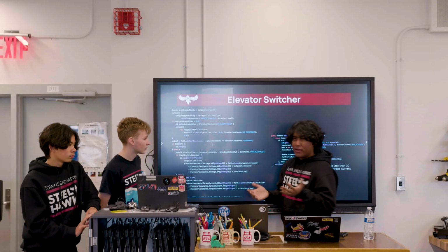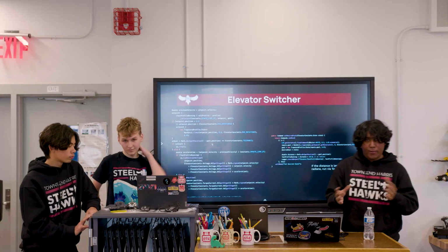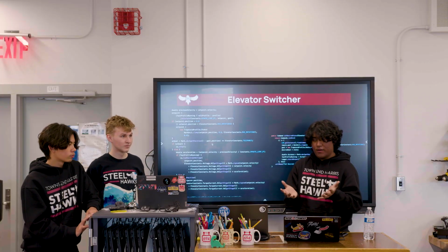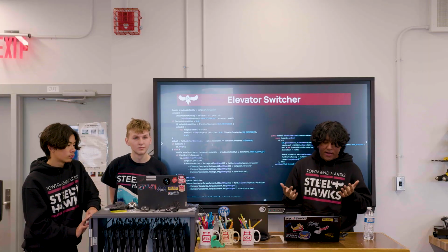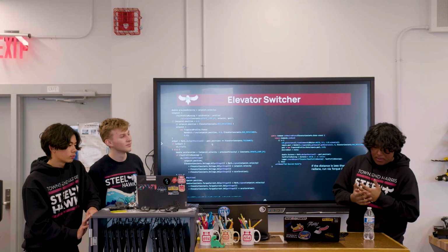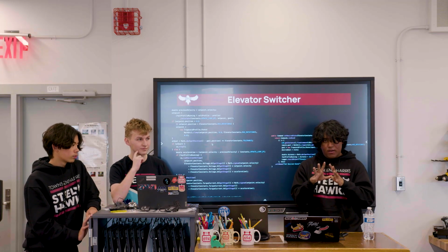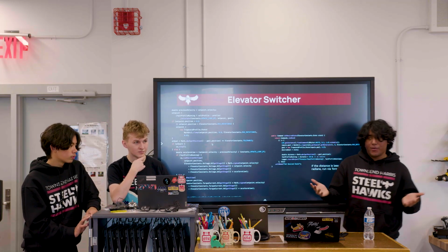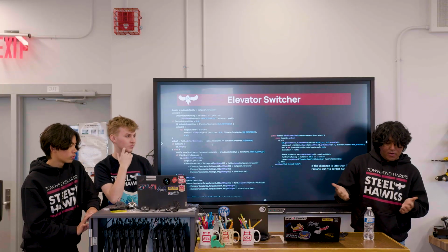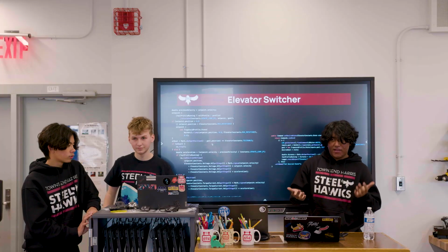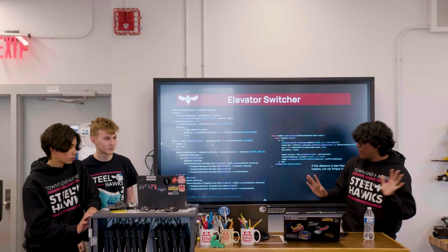Everything we use is going to be motion profiled on the robot reel instead of the motor itself, but we run PID on the motors. There's a reason for that: we're planning to have a continuous elevator, and your feedforward values will change depending on what stage you are at. But you're not able to change gains like that on the fly if you run motion profiling on the motor, but that's besides the point.